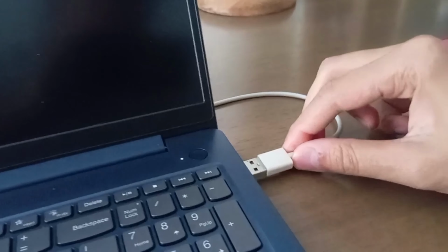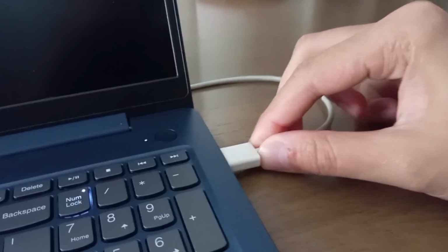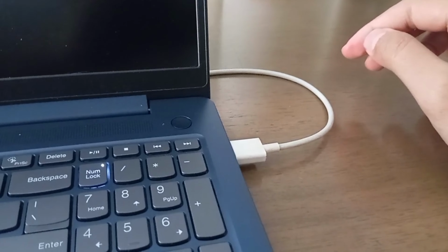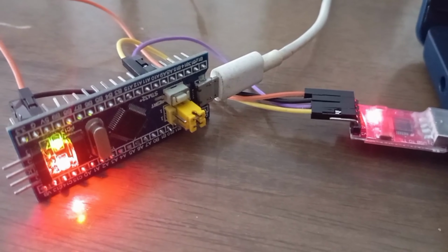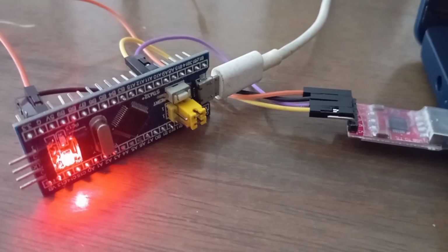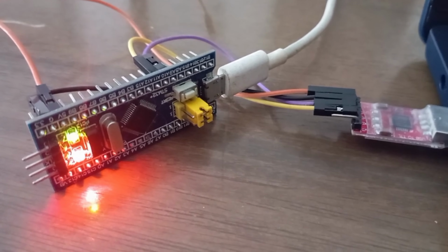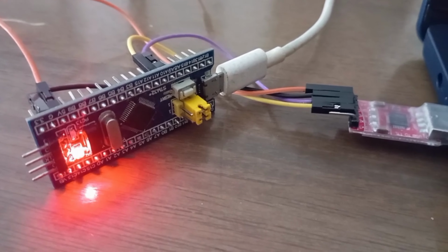Go ahead and just remove the programmer, the CP2102N driver. Okay, you can see this pop-up: connection is lost. So you can just connect the power. You can see my Blue Pill is blinking here, so it just works fine. And yeah, guys, that's it. If you want to hard reset, just go from BOOT0 to BOOT1. Then you just click on hard reset. Yeah, that's it. That's flash.